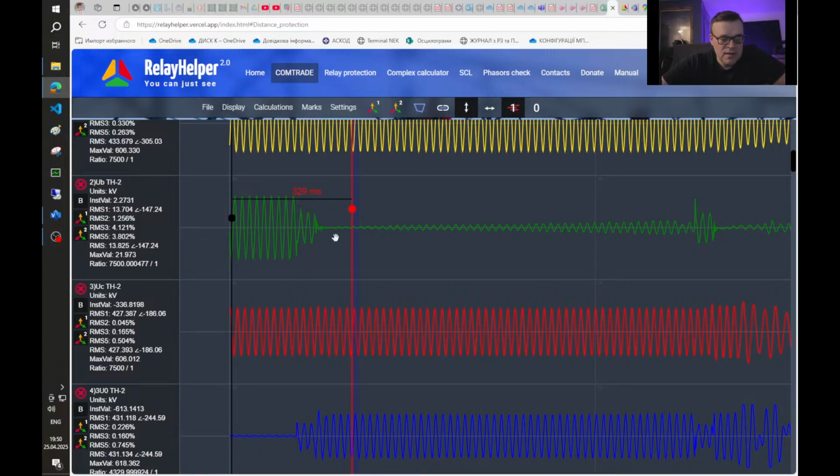So these are signs that the arc went out, and we can close the phase, but it depends, because of the shunt reactors this time is very slow, and also this line is not very long at all, it's just a little bit more than 300 kilometers.